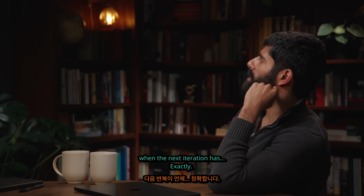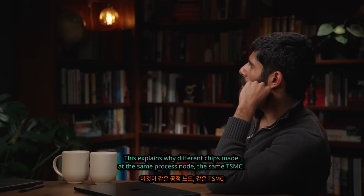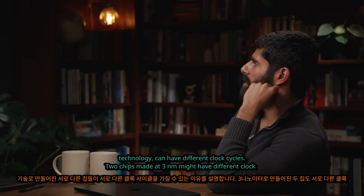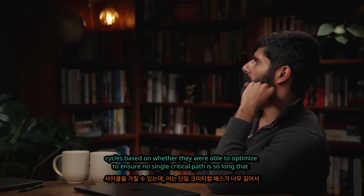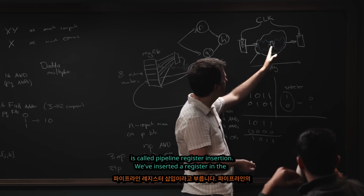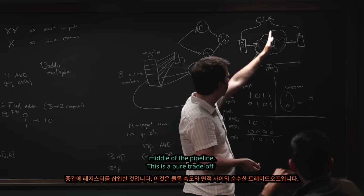Exactly. Yes. And so this explains why different chips made at the same process node, the same TSMC technology, can have different clock cycles. Two chips made at 3 nanometer might have different clock cycles based on whether they were able to optimize making sure that there's no one critical path that is so long that it slows down the whole chip's clock cycle. That's right. This optimization that I showed here is called pipeline register insertion. We've inserted a pipeline register in the middle here.